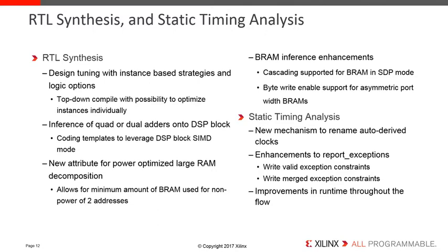There are a number of improvements and enhancements in the area of synthesis and physical implementation in Vivado 2017.1. RTL synthesis now provides the ability to optimize the design using an instance-based top-down compilation approach. There are preset strategies to optimize based on area, performance, or routability, with additional logic optimization options that can be specified by the user. Additionally, inference of quad or dual adders onto DSP blocks, new attributes for power-optimized large RAM decomposition, and BRAM inference enhancements features are available.